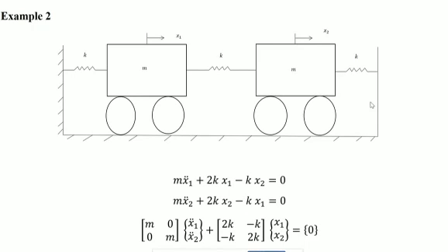And the body is also vibrating, undergoing pitching, yawing, rocking, all kinds of motion, and of course rocking is much more. So these are the next modes or next natural frequencies. But the first natural frequency is zero.